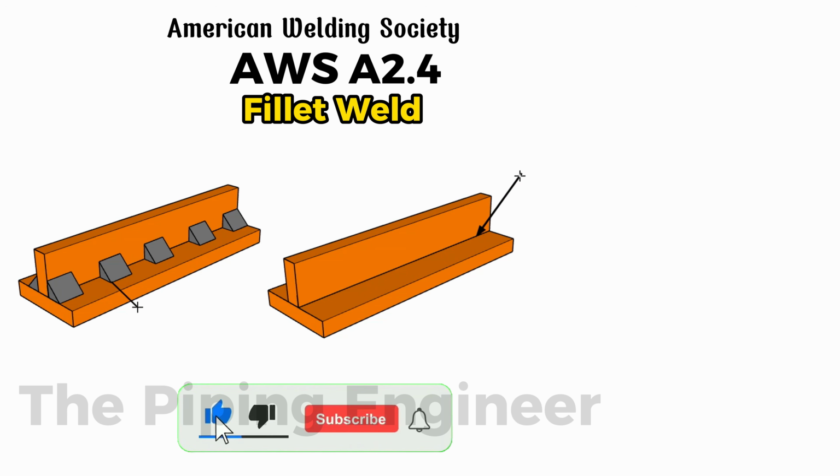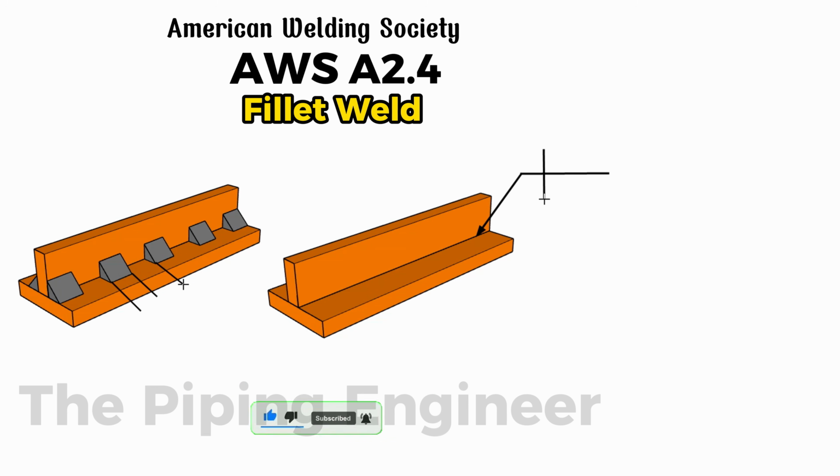Just like normal, the leg size of the fillet weld is written right in front of the symbol. But over on the right side of the symbol, you'll see two numbers showing you the length of the weld and the spacing or gap between them. Let's look at an example to break this down in more detail. If you see an 8 on the left side of the symbol, that means the leg size, the length of one side of the fillet weld, is 8 mm.